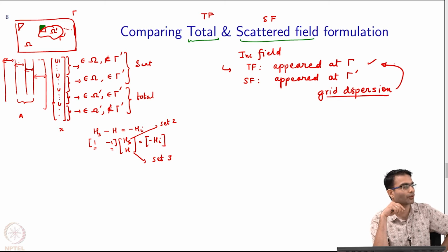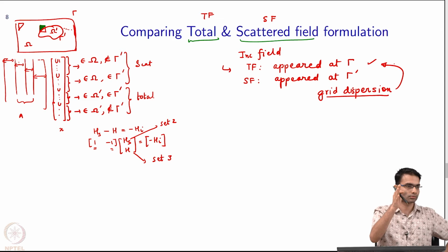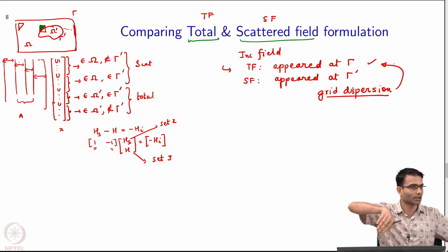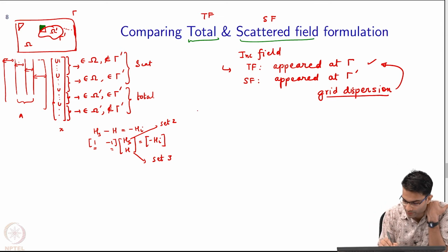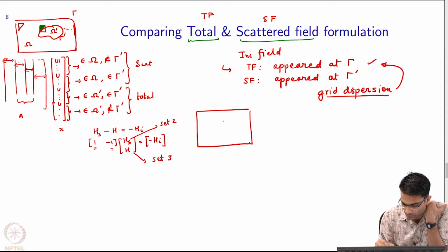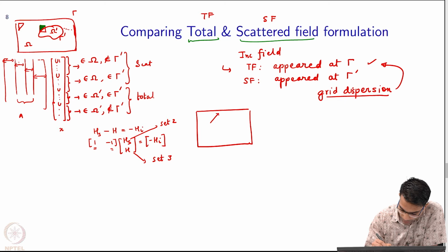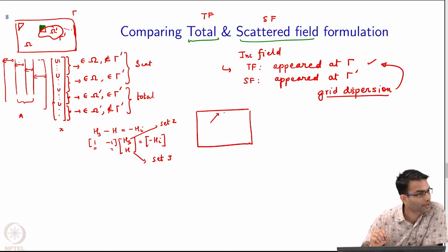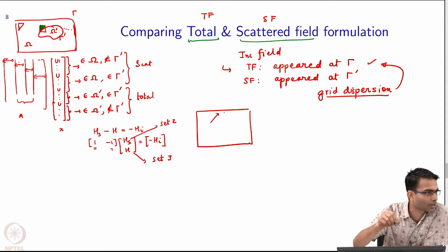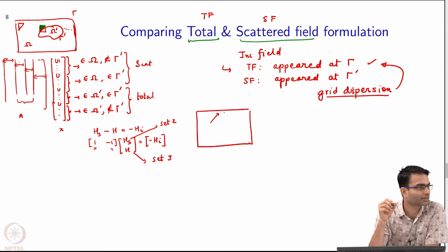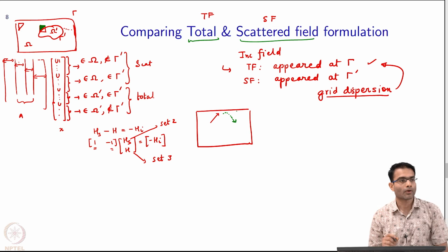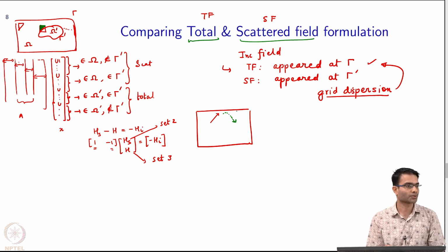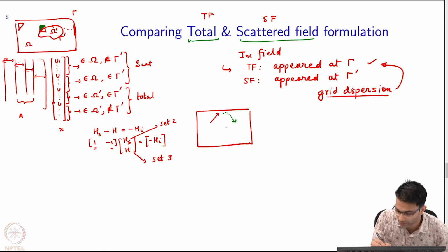we have spoken about this radiation boundary condition being inexact, correct? And it is inexact when the field that is hitting it is non-normal, not coming at 90 degrees, then something reflects back, correct? Now, as an engineer, if you wanted to make that situation better, let's draw it once over here. So, right now it does not matter whether total field or scattered field, some wave has come over here. This is true in total field or scattered field. Even in the scattered field formulation, I am imposing the boundary condition, the RBC, which is correctly true only for normal incidence, not for non-normal incidence, right. So, some amount of this is going to get reflected. Now, as an engineer wanting to reduce this, what other option might you try? This is the numerical reflection.